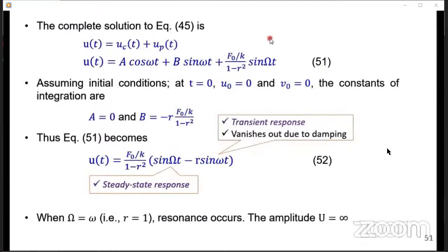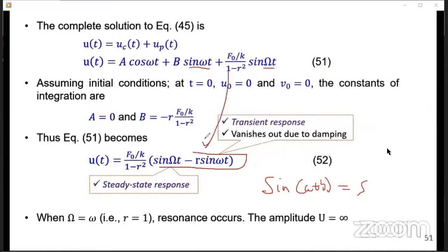Here we have just jumped some steps, because if you remember, there are identities that we utilize to simplify our motion, the identity for sine of A plus B: sine A cos B plus sine B cos A. This is what we have done in this case, because we have sine omega t and sine Ohm t. We expand, and then express it in a compact form as this. So there is a step you need to do after obtaining A naught and B naught: you substitute them here, this collapses, and then we rewrite these two different components in this form.